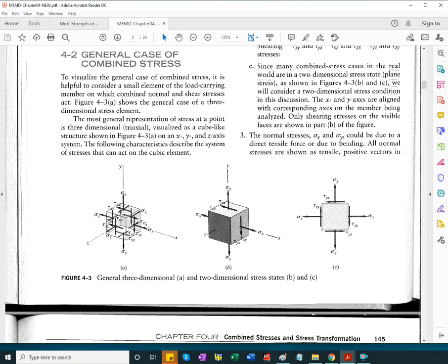If the stress is away from the surface, it's positive, and the index is that of the axis. If it's a shear stress, then the first index is of the axis it intersects, and the second index is the axis along which it is oriented. Compressive stresses are towards the surface. Here, all normal stresses are positive. There's a stencil.